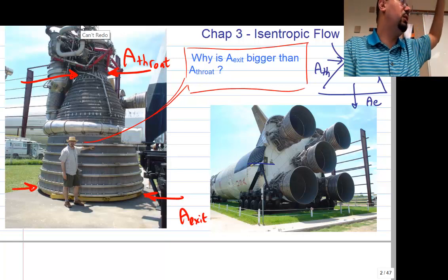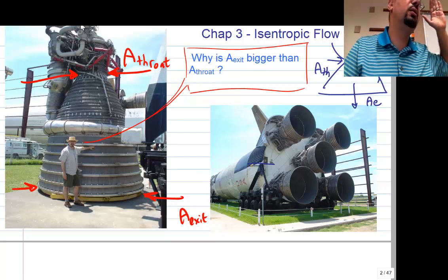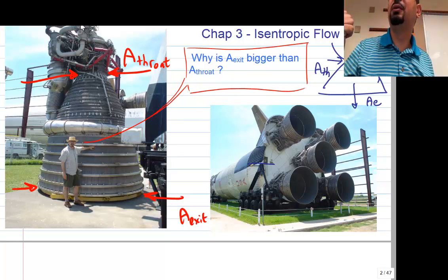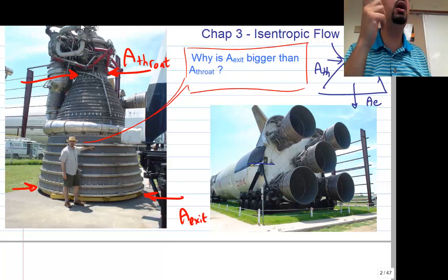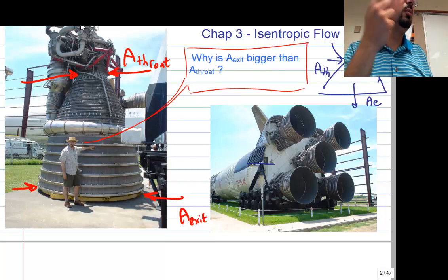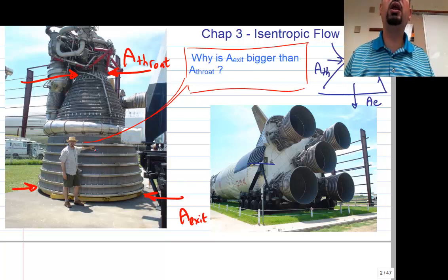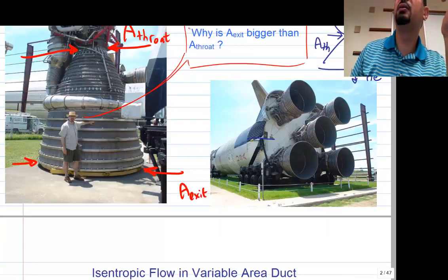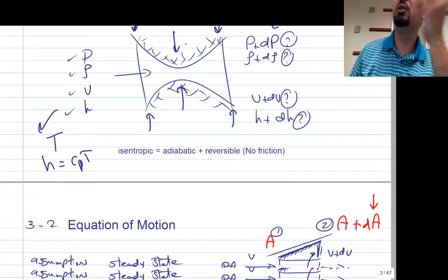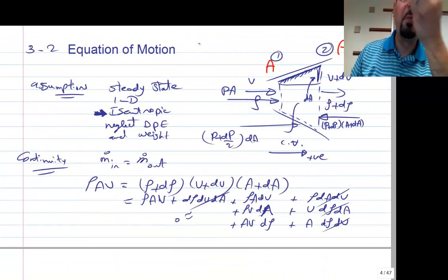It's nothing. Those 10 meters of air, especially if it's air, not water. So potential energy, when it comes to water, it's a big deal to neglect 1 meter of water, for example. But it's very easy to neglect 10 meters of air in the energy equation, especially when there is a huge change in kinetic energy and pressure.